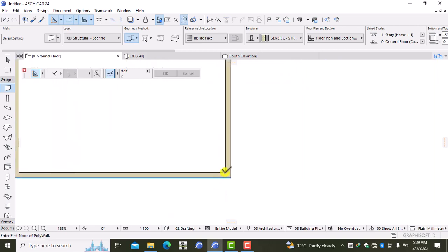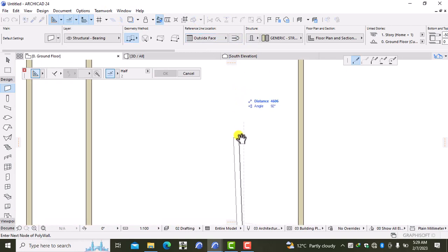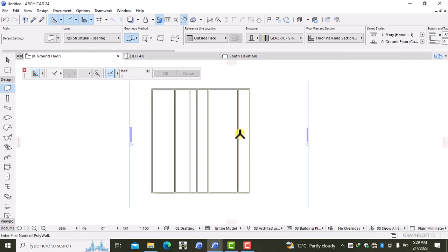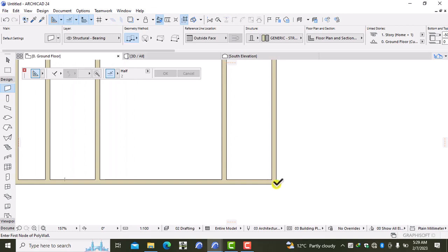And then from there, also have another wall right over here. Set a distance of 2000 from this end. So go ahead and just click 2000. Press enter. This time we're not going to use the inside face, we're going to use the outside face. So something like this up to that point. And then from there I can also do another wall, we can start from this point. I'm coming to this right corner over here, and I want to drag it to do a wall at a distance of 5700. So I just key in 5700, just press enter.